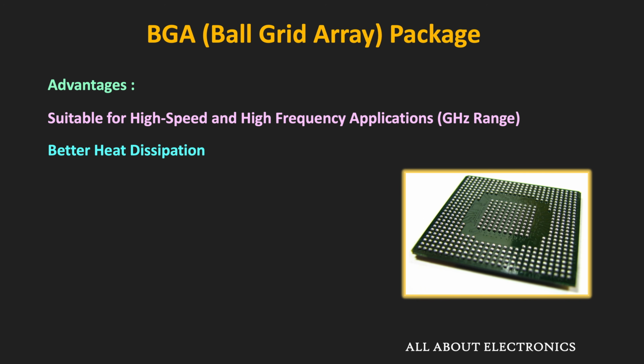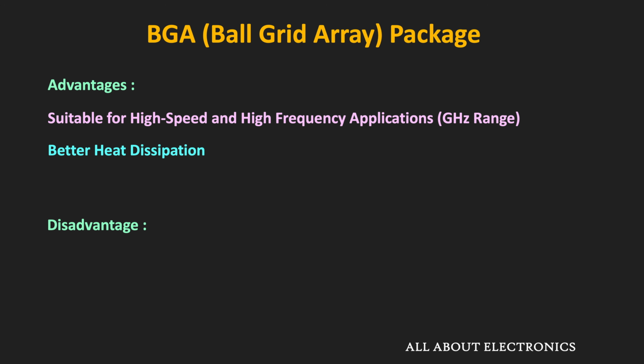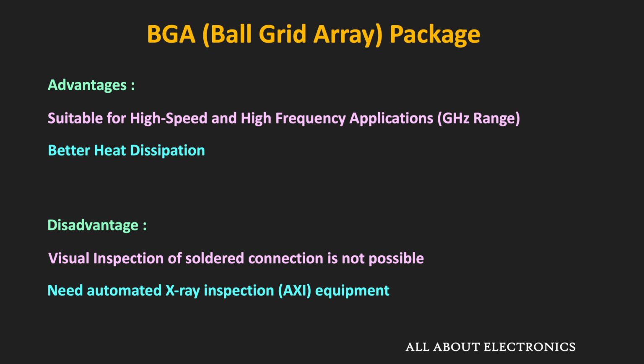Now the only downside of this package is that as the solder balls are beneath the package, visual inspection of the soldered connection is not possible. And therefore, for the inspection it requires special X-ray equipment.